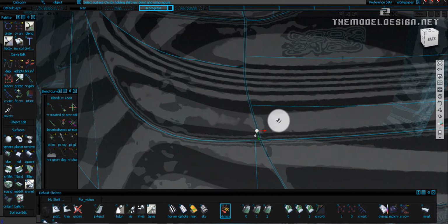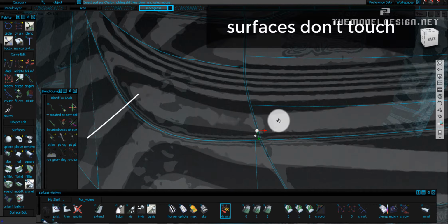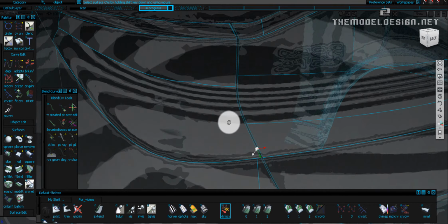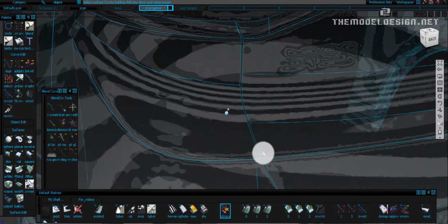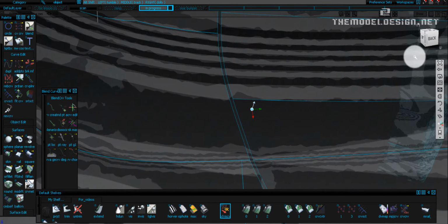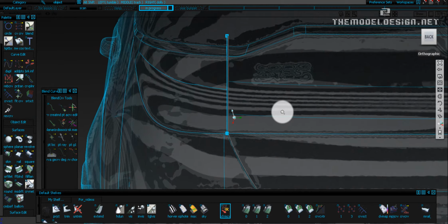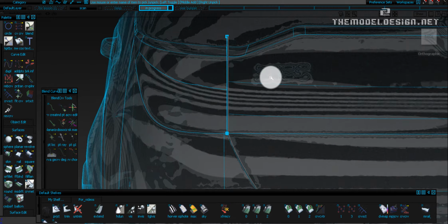Basically, the highlight of our corner blend had to match the existing highlight of the sill surface created in tutorial 1. And also the second challenge was to achieve a decent theoretical intersection. In this place, unfortunately, these two conditions played against each other. When I managed to achieve a good highlight, I lost a good theoretical intersection, and vice versa.